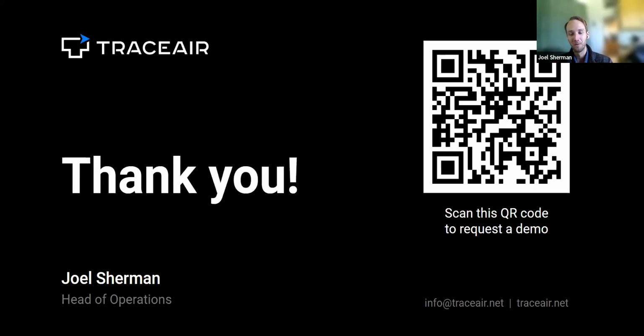Again, if there needs to be a very accurate profile of the earthen surface in some large ponding areas, then it would make sense to wait for those ponding areas to be fully drained to derive the elevation model you're looking for. So LiDAR, the innate sensor, will not tell you it's water or dirt. The person interpreting that data, and that's why we have a human in that chain of processing the data, determines and classifies which points should be thought of as actual earthen surface versus not. I hope that answers the question you're looking for, Chris.